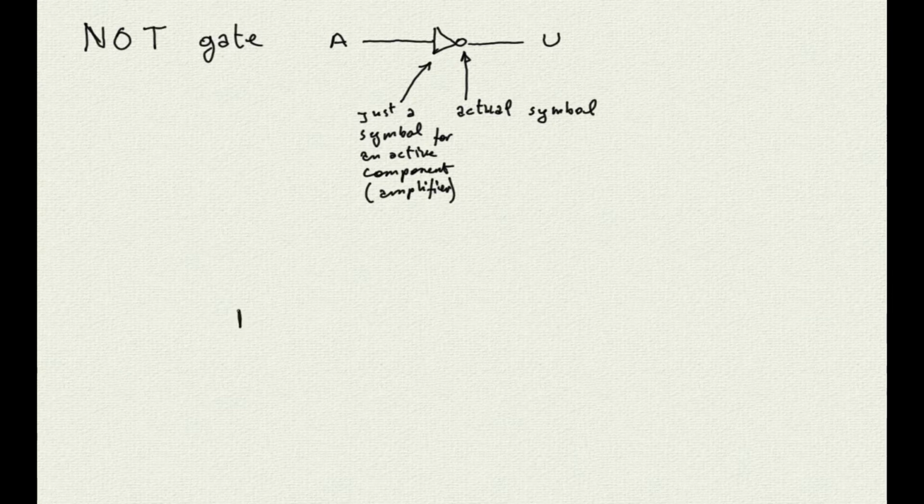And in fact, the NOT gate is made of a simple transistor polarized in such a way that it works in only 2 possible states: off or open, where it does not conduct any current, and on or closed, where it does conduct enough current to be in saturation. To obtain this behavior, we just need a couple of resistors, one on the collector to limit the maximum amount of current, and one on the base to limit the current that goes through the base emitter junction when the base is positively polarized. And so this is the whole schematic of a NOT gate.